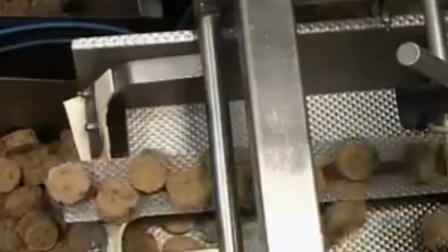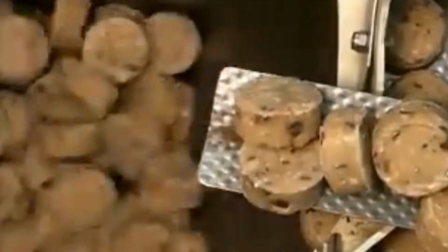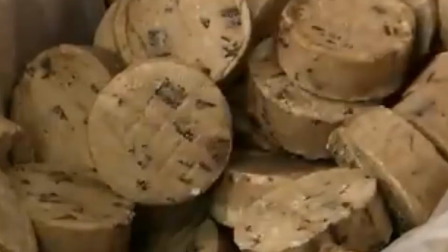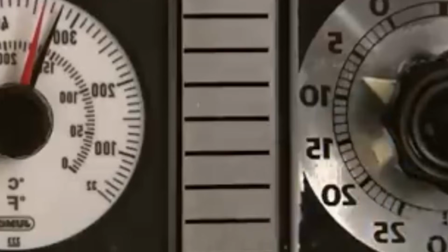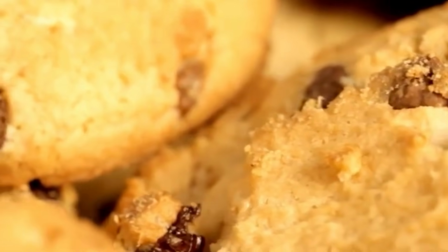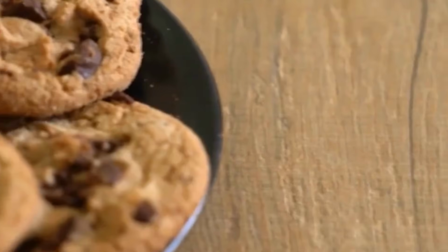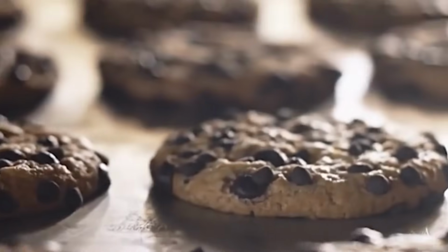Flow wrappers are equipped with film tracking systems using edge guide sensors to maintain alignment. Tension controllers manage unwind force to prevent film distortion. Cartoning machines feature vision systems that verify correct pack orientation before loading. Misoriented or missing packs trigger reject mechanisms that divert affected cartons to inspection lanes.